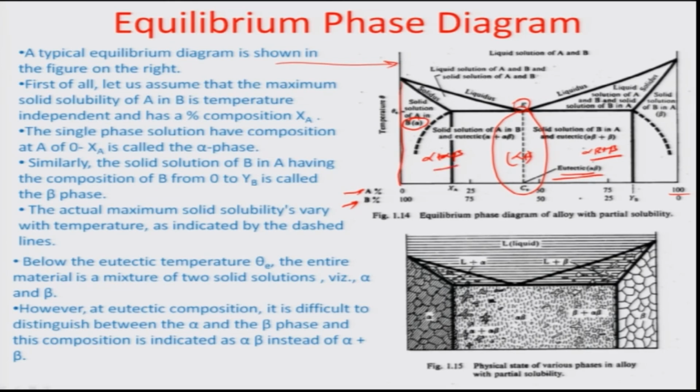So, that is in a similar manner to the ice system, we are trying to generate information from this in this manner. Okay. So, you can think of it that this is the indistinguishable phase, the eutectic phase, this is the hypereutectic phase, and this is the hypoeutectic phase comprising of beta plus alpha beta and alpha plus alpha beta respectively. So, these are the phases where you have complete solid solutions of alpha structure or complete solid solutions of beta structure.